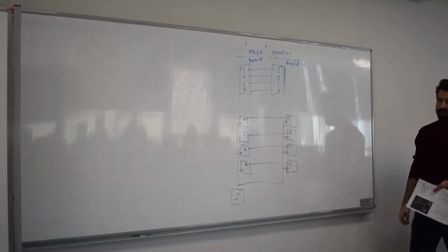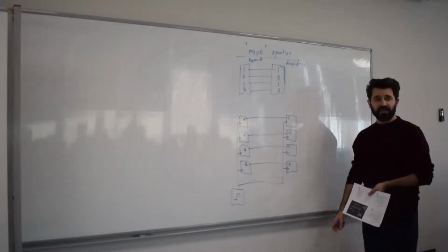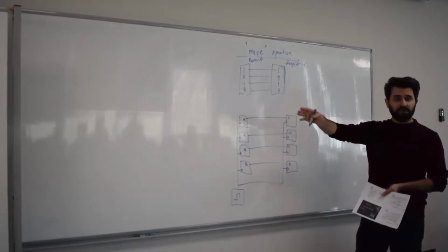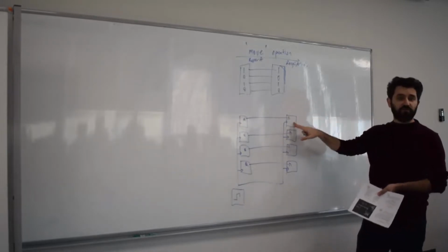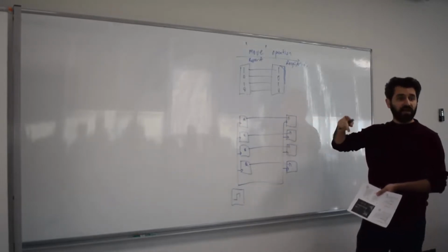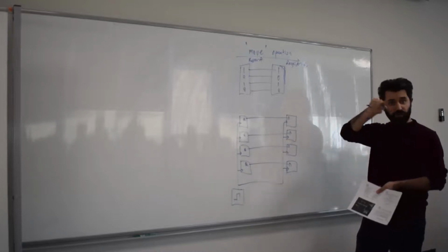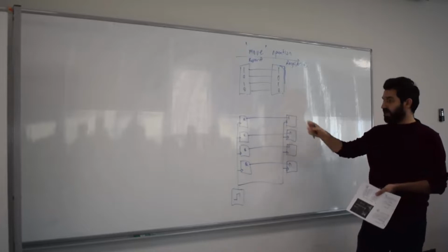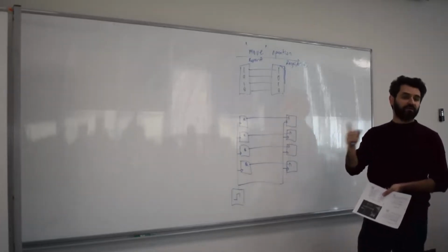But the problem with the D flip-flop is that if you would like to store the same value for as long as you want, there is no such state in the D flip-flop's truth table, if you remember, right? JK and T have that Q value in their truth table or state table. However, D does not have it. D can be set or reset. It can be 0 or 1.